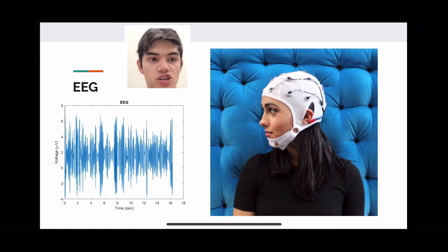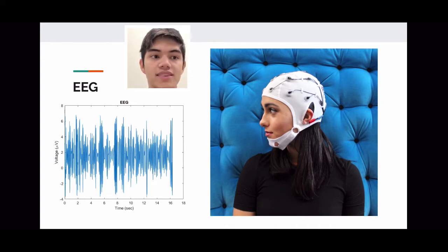Electroencephalograms, or EEG, analyze brain activity by measuring scalp voltages using electrodes placed about the head. Previous work indicated that the primary motor cortex is an easily identifiable brain signal by EEG, and because either side of the body is controlled by only one side of the brain, relative activity between both sides could be used as the raw signal that will be processed into a command signal.